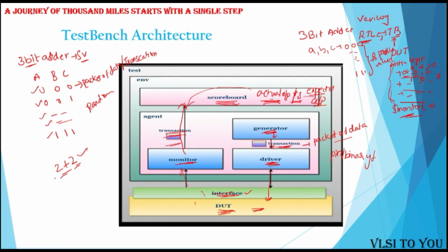Now all these components, generator, driver, monitor, and scoreboard, are packed within the environment. The environment is again packed within the test bench. Then come the test cases. These test cases are, for example, when you are designing a memory. Here it is just a 3-bit adder.